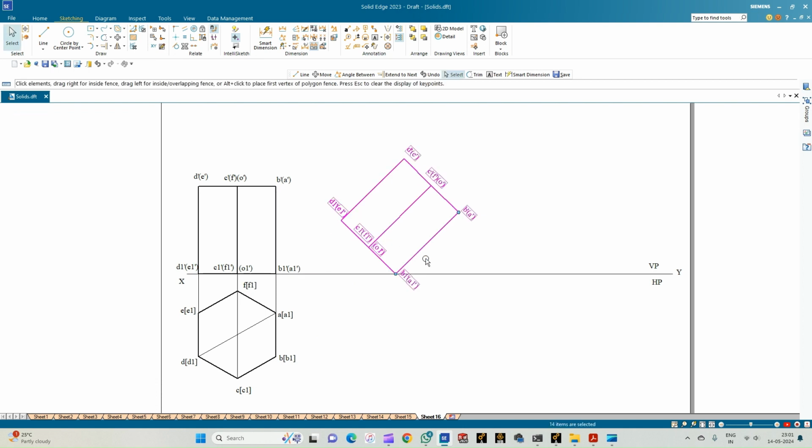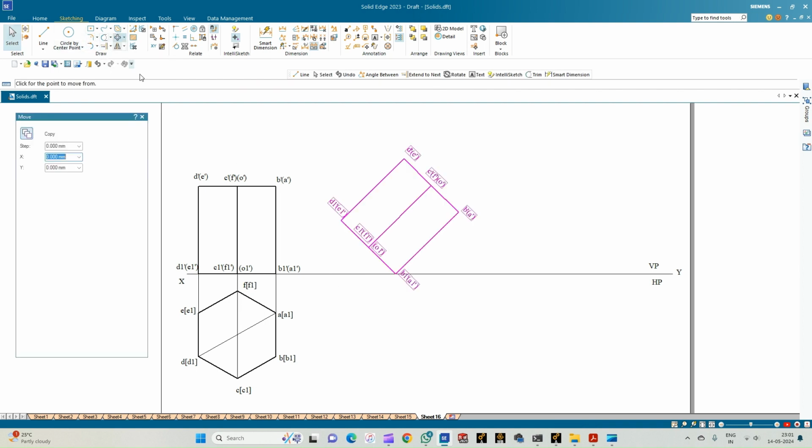So we're going to incline the base at the angle of 90 minus the inclination of the axis line with respect to the HP, which will be equal to 45. So we'll just move this so that we have got sufficient place to complete the third position.